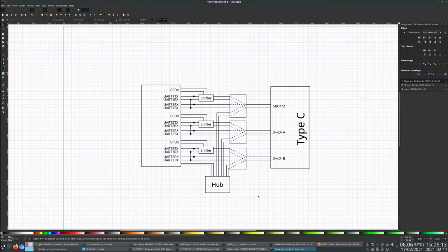But I don't think we need pull-ups for the Mac use case. And yet, it would make sense for I2C to be on the 3.3 volt pairs because the I2C is 3.3 volts, so that would work without the shifter. I2C behind the shifter is wasted, basically. That's never going to work. Yeah, unpopulated resistors is probably a good idea.